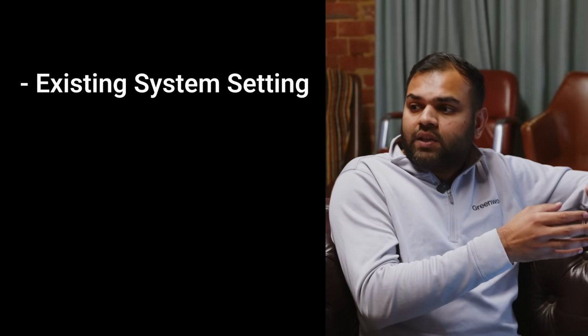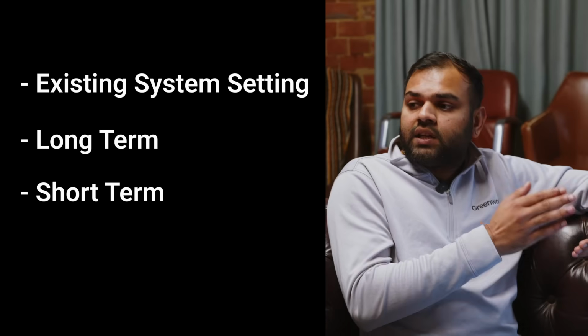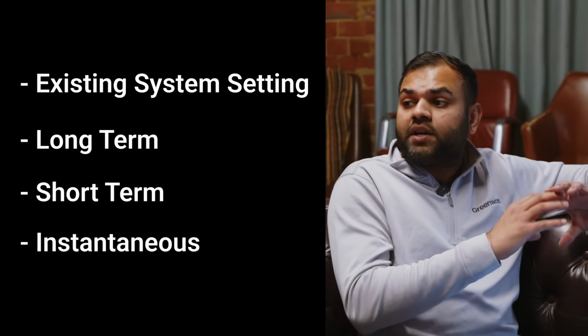actually present on site. Right. For the existing system, which can be long-term, short-term, instantaneous, and ground fault settings, which are already present at the site. And then when you are performing this study, you adjust the PV system settings or PV system breakers settings. For example, here 1000 amp breaker as well as 5 of the 200 amp breakers settings to coordinate with the main switchboard or the existing system. So basically you get the settings of the PV system main switch as well as the inverter breakers which are coordinating with the upstream or the main switchboard.